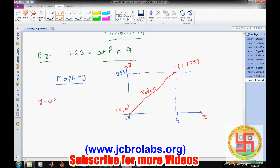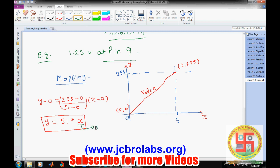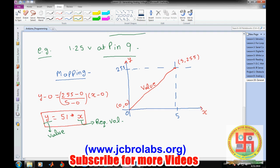So y minus 0 equals 255 minus 0 divided by 5 minus 0 into x minus 0. So this will be y equals 51 into x. This x is the required voltage which we want to generate, and y is the value which we have to pass into the analogWrite function.